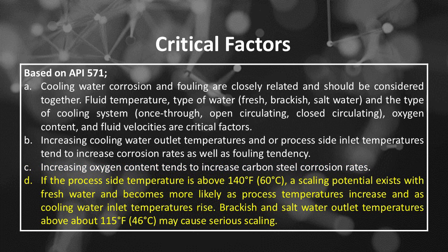Number D, if the process side temperature is above 140 degrees Fahrenheit, or 60 degrees Celsius, a scaling potential exists with fresh water and becomes more likely as process temperatures increase and as cooling water inlet temperatures rise. Brackish and salt water outlet temperatures above about 115 degrees Fahrenheit, or 46 degrees Celsius, may cause serious scaling.